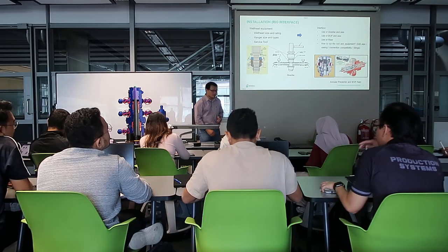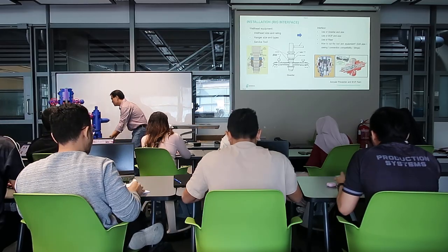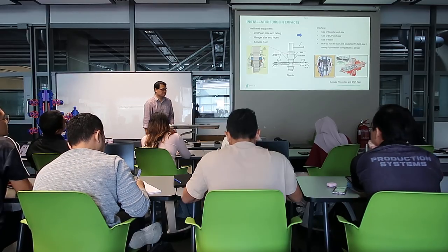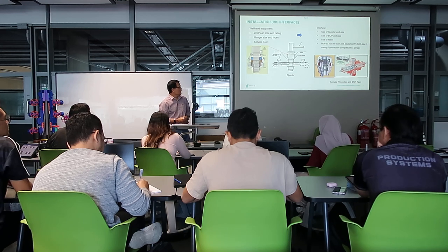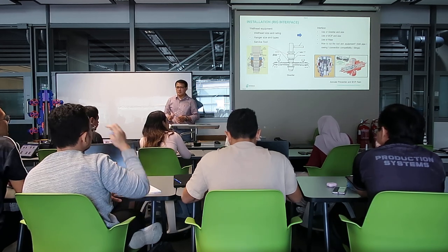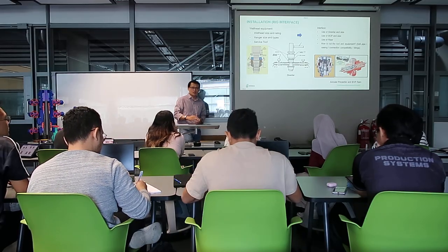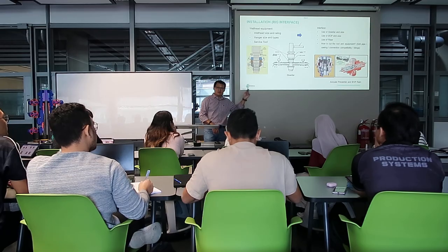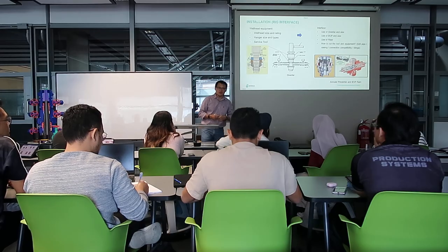So we talk about the interface, the rig interface. So just now we talk about diverter and BOP. So what are the diverter and BOP? They are actually different pieces of equipment which are required at different stages. So by right, diverter is only to divert the flow. We cannot shut in the wells with diverter. So what happens is when we